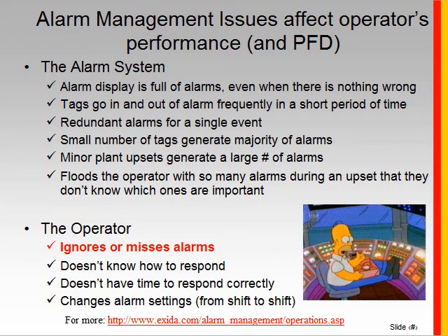Certainly if the operator's console is full of alarms all the time, and you've got alarms that go in and out of alarm with a high frequency, if you've got situations when one event occurs and you've got multiple alarms always being presented to the operator, those situations are going to get in the way of the operator making a clean, clear view of what's going on and an accurate response. Now, when it comes to the operator, if they don't know how to respond to the alarm, or we don't give them enough time to respond, that's also going to affect their performance as well.